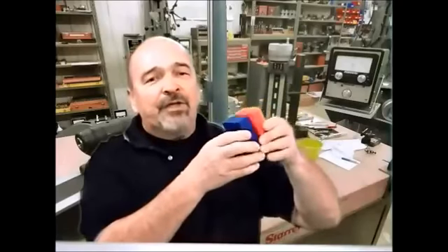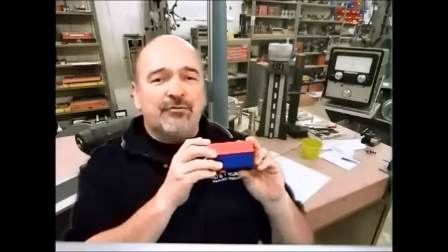At first, these might seem confusing, so to clear it up, we've created a reference card and models to explain the various envelopes. An unrelated actual mating envelope, like this pin, and its axis, would be used to establish a primary datum or to find the position of this hole. However, a related actual mating envelope, meaning related to another datum, is used for a secondary or tertiary datum feature to establish datums and calculate datum shift, where these datum features were modified with the M or L in a circle. If you're not using these envelopes, you may be introducing too much uncertainty into your inspection results.